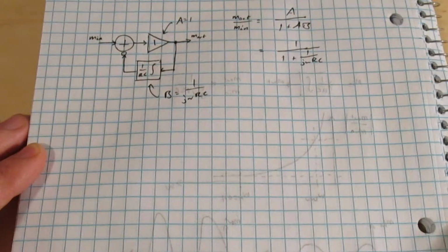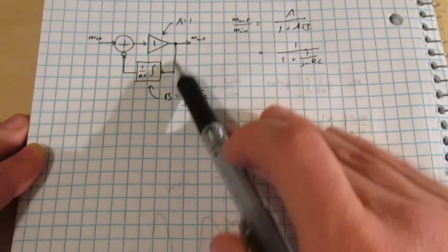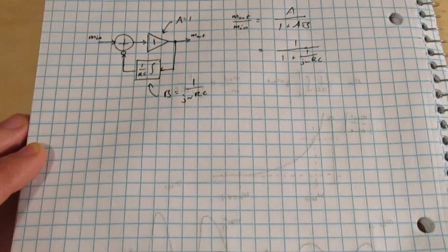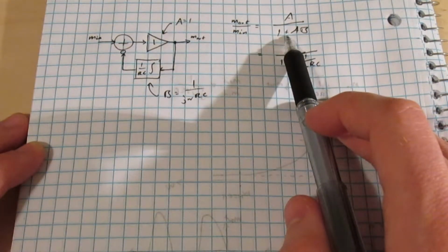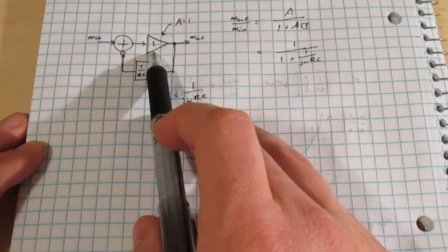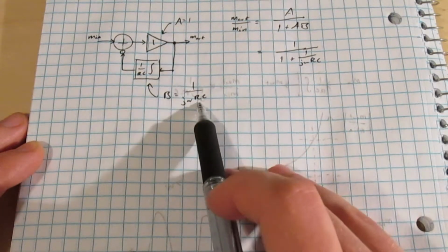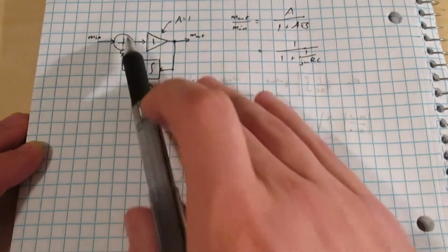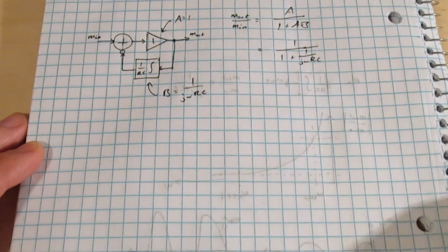And one last bit of background before I get into the actual circuit is what the frequency response looks like when you use the integrator in the negative feedback. This is the general form that the DC offset tracking has in the ECG circuit. So from a bit ago we have this expression here for the gain of an amplifier that has negative feedback. In this case our amplifier gain A is going to be 1, and the gain of the block in the feedback path, which is the integrator, is 1 over j omega RC. And when we plug those back in, we get a total gain for this entire system of 1 over all of 1 plus 1 over j omega RC.